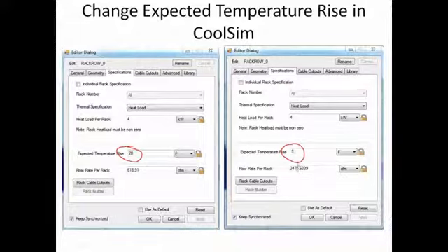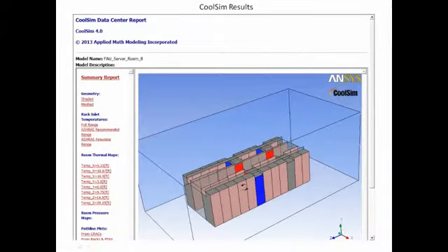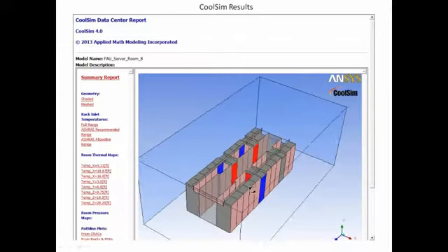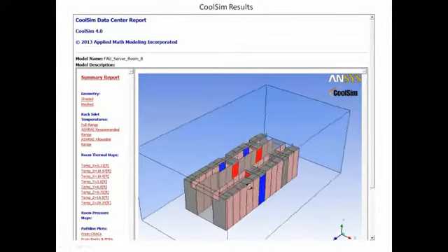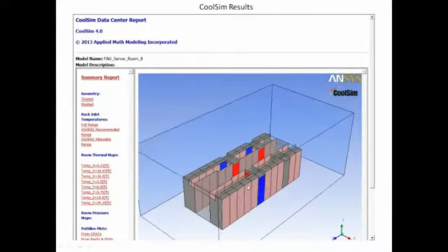So to adjust the model, you just look at what was measured, and we saw a measurement of 5, delta T of 5, heat load still 4, and you see the flow rate per rack automatically adjusts to 2475 CFM. And that's how you do it. You do it for each one of the racks. And this is a set of results that came from that run once we did the calibration. And what's kind of interesting here is that these temperature measurements line up quite nicely.